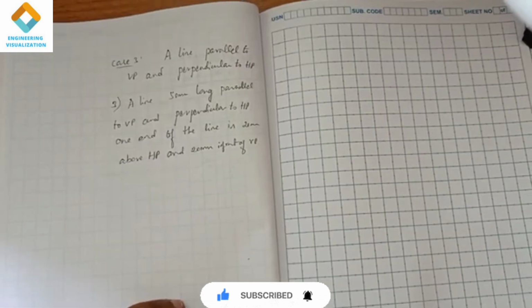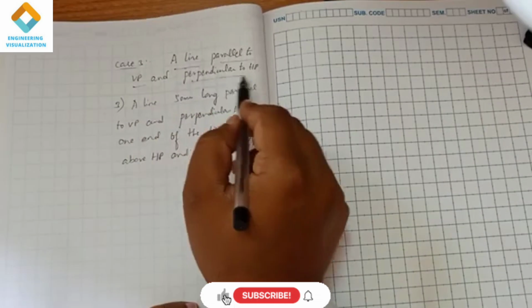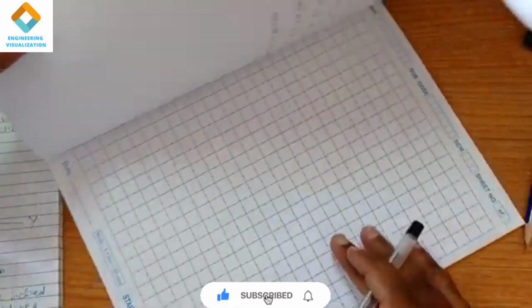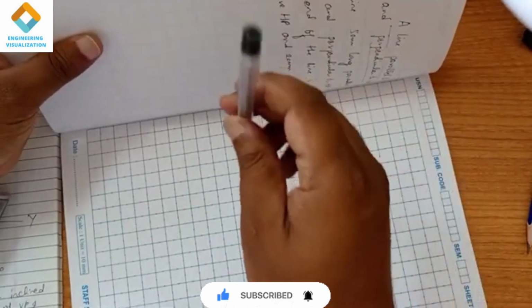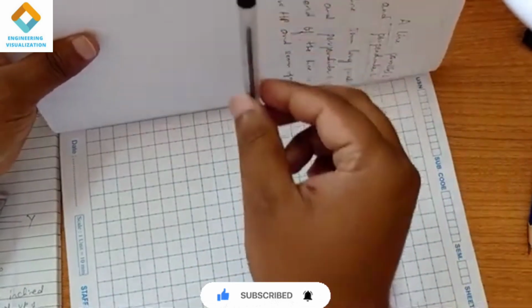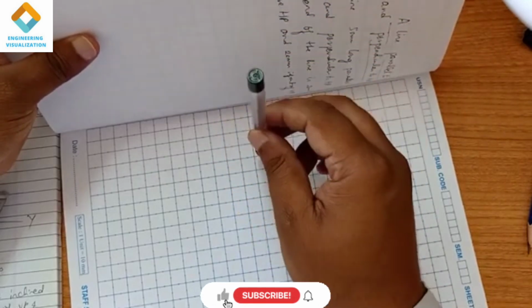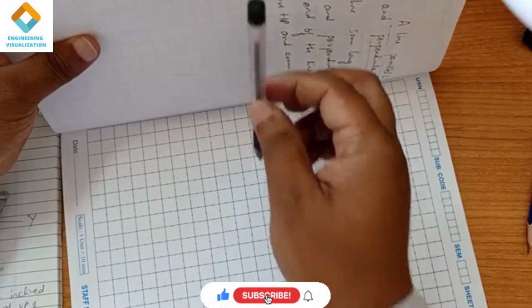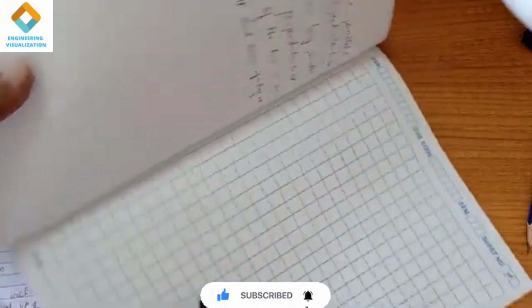Let us see the third case. The third case is a line parallel to VP and perpendicular to HP. How to do this condition? Here this is our vertical plane and this is the horizontal plane. In this condition the line is parallel to VP, so we get a straight line in the VP plane, and perpendicular to HP means we get a dot in the HP plane. This is the condition, parallel to VP and perpendicular to HP. Like this we have to do.